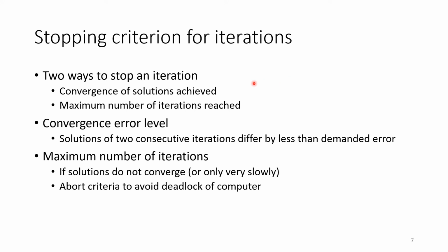Every iterative process, and this is very general here, it's not just about the groundwater flow module in GRASS GIS, usually has two kinds of stopping criteria. I mean, it needs at least one, but usually has two. One is your convergence level. In an iteration, you start with the first guess, your initial conditions, you do your calculations, and then you compare the result to the first guess, your input model.